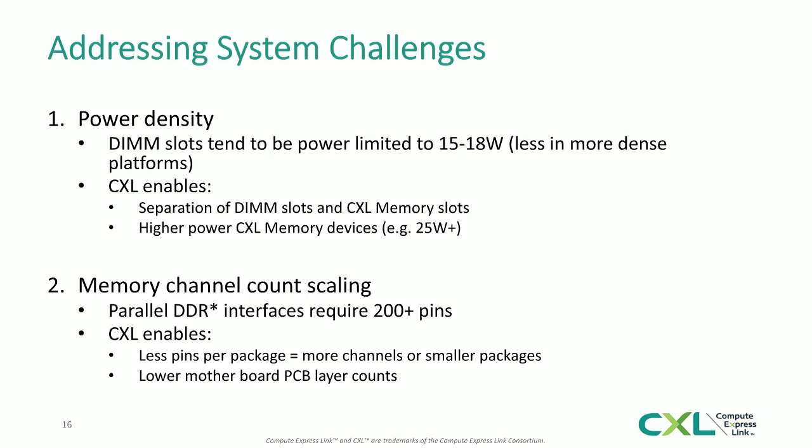And then finally, because we're now talking about a serial interface with a much longer reach potential, you can also place the CXL memory in different locations. It no longer has to be sitting right next to the processor. You can put them in more optimal locations, which allow you to also optimize things like the airflow across these CXL memory devices.